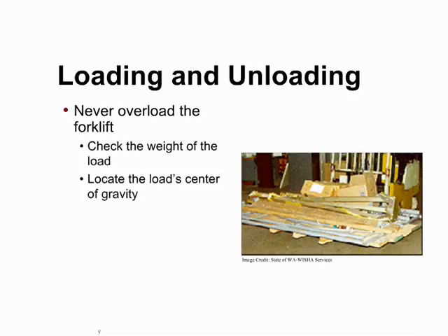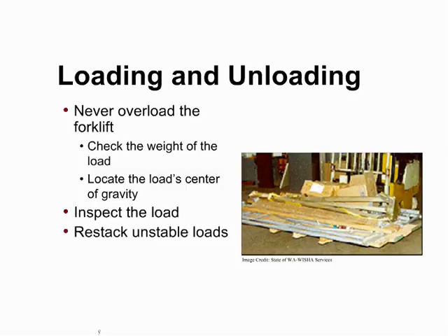Be sure to locate the center of gravity of the load. Inspect the load for stability, projections, and damage to pallets before lifting it. If the load is unstable, restack it, and if necessary, secure it with straps or ropes. For a wide load, spread the forks as wide as possible so that the load will fall inward if it becomes unstable. Only use the rear towing pin for towing. Never drill a hole in the forks as a way to tow something or as a place for a chain hook. This ruins the integrity of the forks.